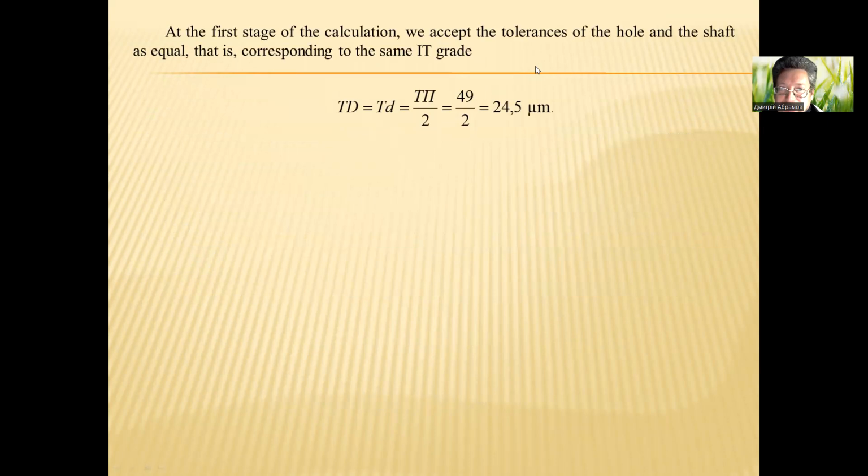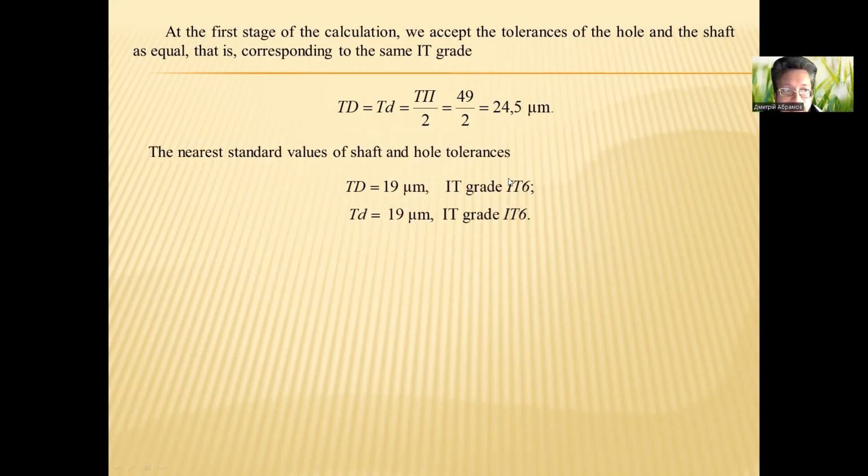The fit tolerance is equal to 49, divided by 2, we have 24.5 micrometers. The nearest standard value of shaft and hole tolerances is IT grade 6.